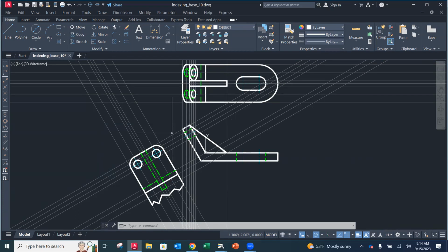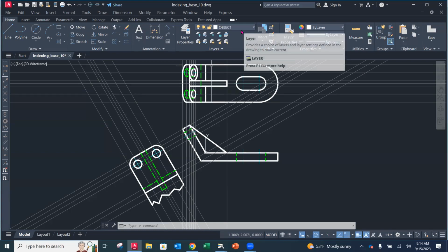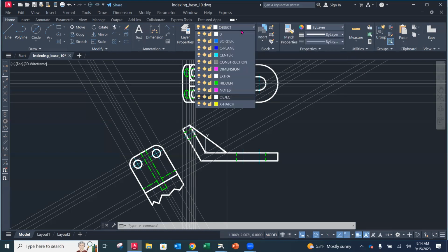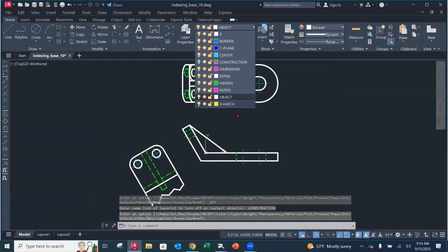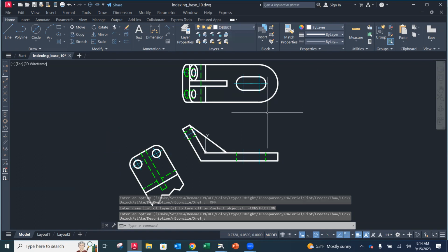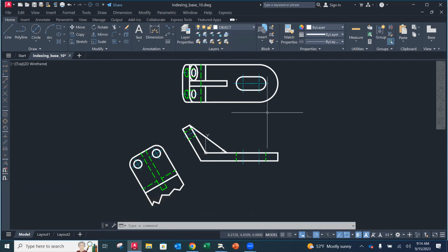Even if you constructed views that were further apart, get them as close together as possible, reasonably. What the distances I have here look good, but I always want you to also turn off the construction lines, because that's not part of your final product. So turn off your construction lines. Now save your part and then upload it to the Dropbox.